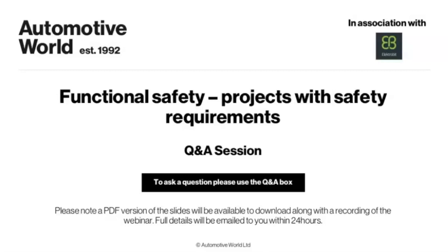The software part which implements this requirement inherits this integrity level, so the QM parts would not fulfill requirements which have an ASIL rating assigned. For inherited reasons, you need to take certain measures, and that is freedom from interference.